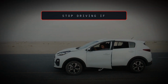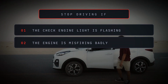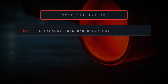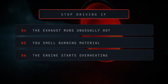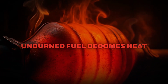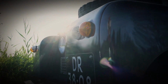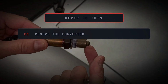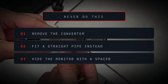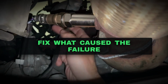Stop driving and have the vehicle inspected immediately if the check engine light is flashing, the engine is misfiring severely, power drops suddenly, the exhaust system becomes unusually hot, you smell burning material, or the vehicle begins overheating. A severe misfire can send unburned fuel into the converter and create damaging heat. Do not park over dry grass or other combustible material if the converter may be overheating. Do not remove the converter, replace it with a straight pipe, or use a spacer or electronic device to hide the monitor result. The correct repair restores the emissions system and fixes the condition that caused the failure.